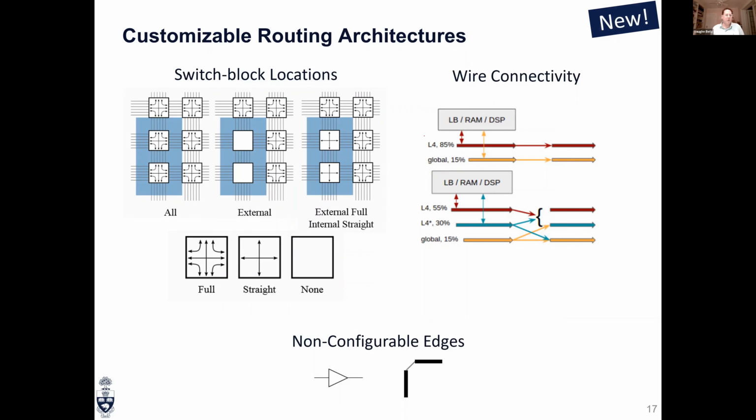Some of the ways that it's been made more flexible in VTR 8 is when you have those large blocks, like that processor subsystem that I talked about, you have a question of, did that processor subsystem block all the wires that went across it? Did it not block the wires? Maybe some of the wires can actually go across it, the usual programmable routing, but none of the switches are there. We didn't want to interfere with the layout of that hard processor subsystem. So we managed to get some wires on the top level metal across it, but we took all the switches out between them. So you can say that's the way you did it.